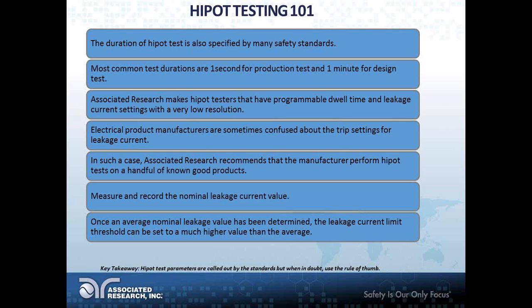Now, Associated Research makes products, or Hipot testers, that have a programmable dwell time and leakage current or failure settings with very low resolution to allow you to set your failure limits very accurately.